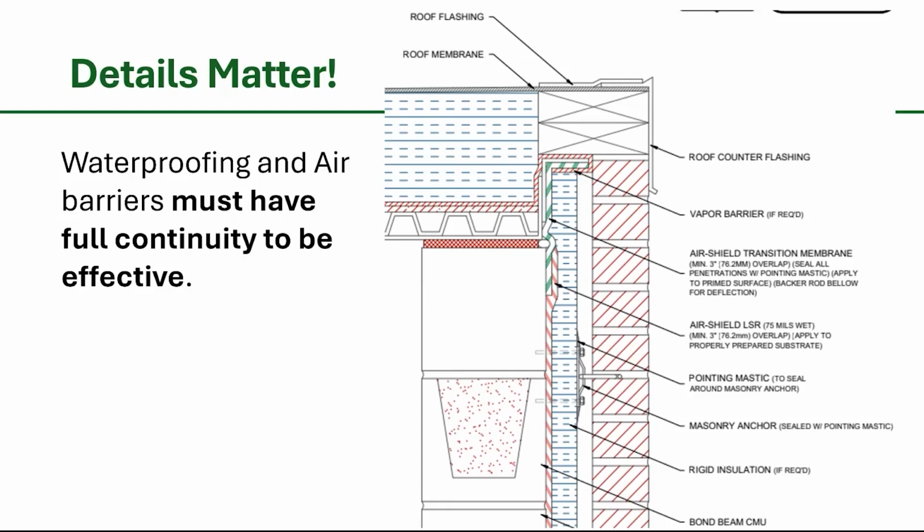It can be done with spray foam. There's a number of ways to do that. The important thing is to take some time at that connection and detail it out. Make sure that the materials are compatible. If the materials are incompatible, you might need a transition membrane. You might need a transition flashing there. And you're thinking in 3D, right? So you're thinking in all three dimensions, do we have continuity?